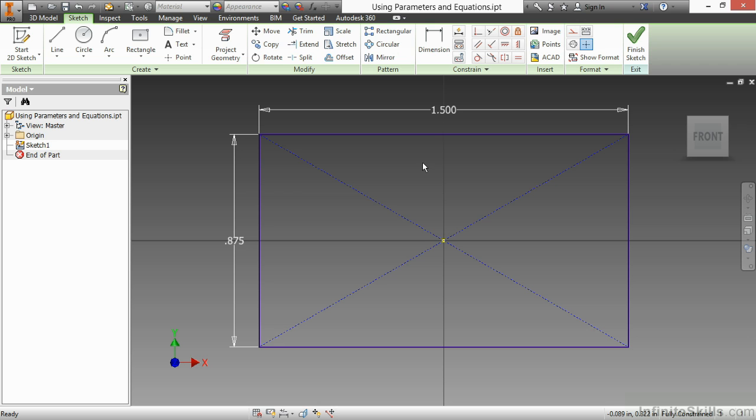I would like to create something a little bit more informative for when I go through design changes, so I can communicate properly with my team what is length, what is width, what is depth. So to begin with, I want to view my dimensions as a name or as a function instead. Down at the bottom of my screen, on my status bar, I'm going to change my dimension display to name, and I can see D0 and D1. Well, that doesn't really help me much. How about I change this to expression? There I can see D0 equals 1.5 and D1 equals 7/8.